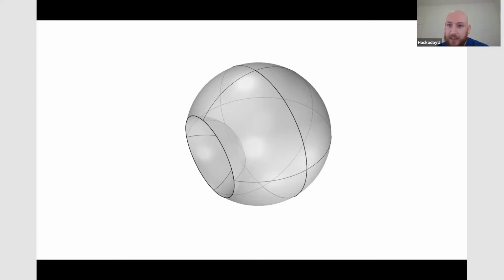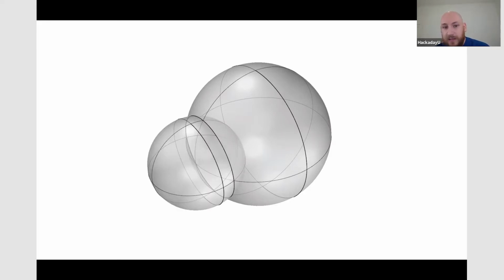But what's really happening from a Rhino perspective, because it only thinks in surfaces, is it is splitting the smaller surface, then chopping that off, then adding that to the big sphere, and then joining them together, and then making that the complete shape.